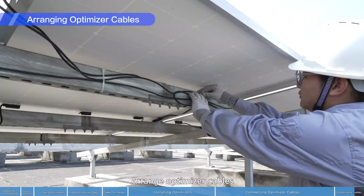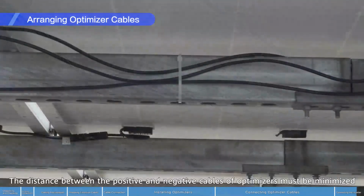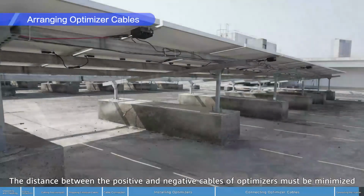Arrange optimizer cables. The distance between the positive and negative cables of optimizers must be minimized.